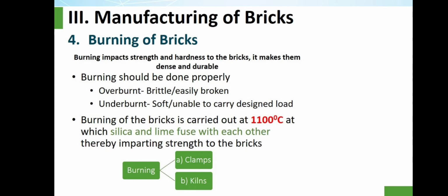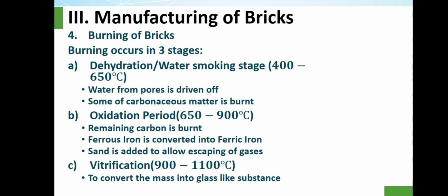Burning of the bricks is carried out at 1100 degrees Celsius, at which silica and lime fuse with each other, thereby imparting strength to the bricks. Burning is done in A. Clamps and B. Kilns.